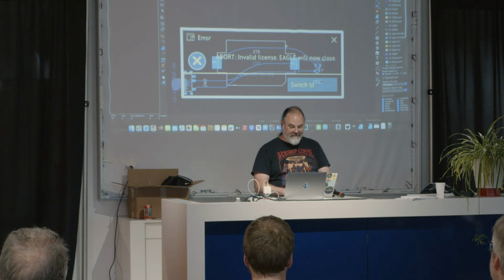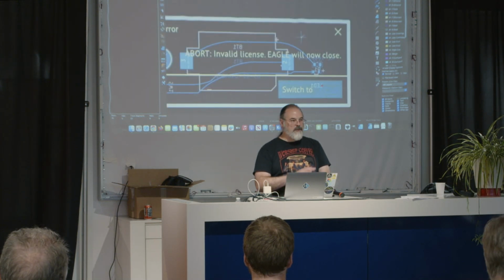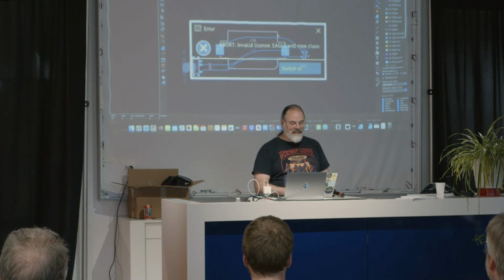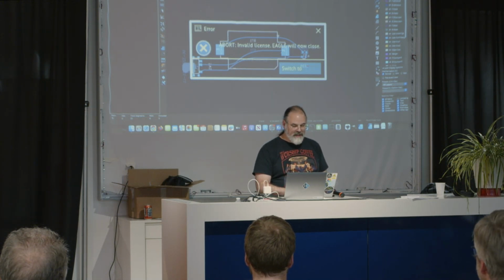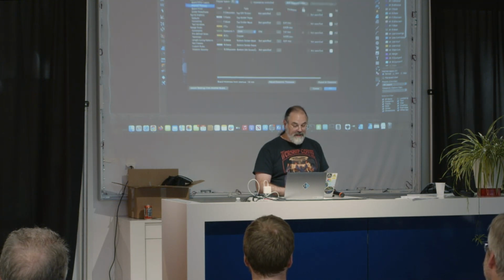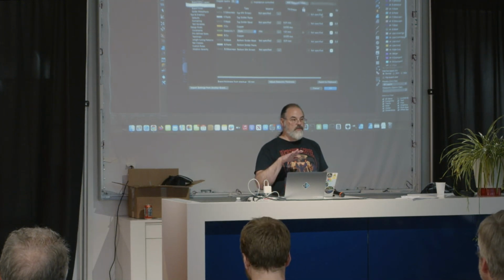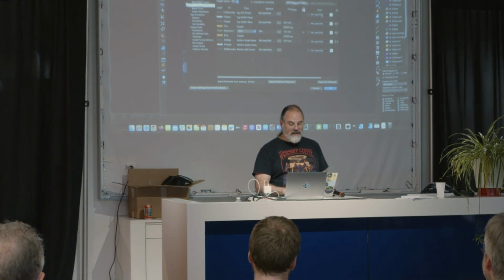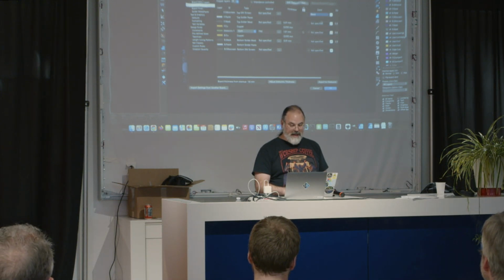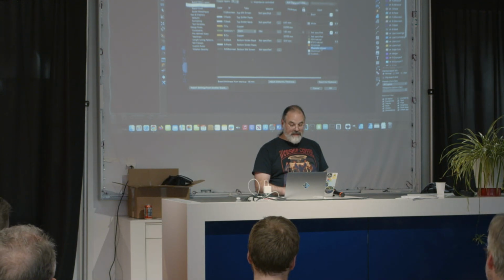All right, so I've wired the board, right? Now we can buy it. Let's eyeball it real quick. Let's see what this would look like. Before I do that, I'm gonna go in here and set some things up because I have a stackup here. And instead of not specified colors, I know that I wanted to go with a white solder mask and black silkscreen. So this is the silkscreen. I'm gonna set black, do white for the mask. The dielectric, I'm gonna say do an FR4 natural. And then again, for the bottom layers, white and black.